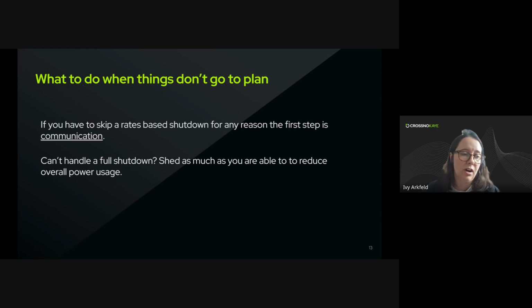and was off for a couple of hours and temperatures are trying to pull back down and you're trying to recover from that. But you have a time of use demand period from 4 to 9 p.m. You don't think you can turn everything off? The next best thing you can do is try to reduce how high that demand is going to be. So I would recommend potentially taking manual action to try to shed evaporators, take off a compressor, whatever you need to do in order to reduce power.